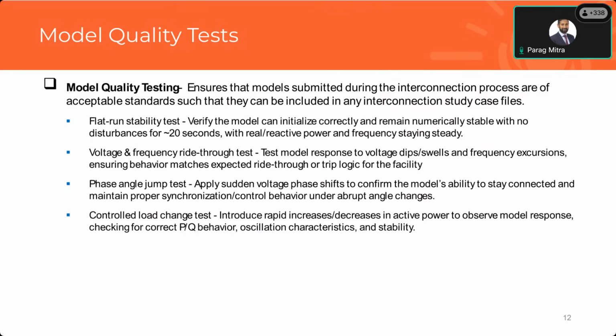The model quality tests are another key component of the whole modeling exercise. Model quality tests ensure that, as a transmission service provider, or an interconnection authority, or a transmission planner, if you're being provided a particular model, the model is good enough to be put in your planning studies, to be used for your interconnection studies and such. So there is a set of tests that one needs to run to make sure that the model is actually good enough to be used in those simulation studies. There is a flat run stability test.